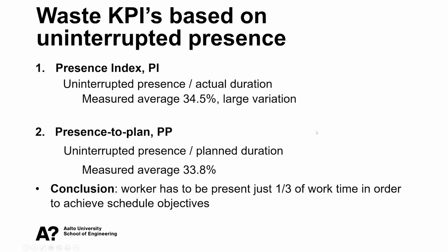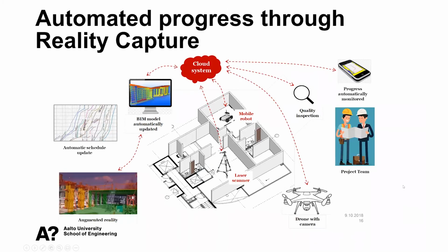Of course, this is just measuring how well you are doing, but to fix this problem, you need situational awareness, basically know what's going on in all locations, and for that, reality capture technologies can be useful. So you can have a lot of different ways how visual data can be captured from projects. Laser scanning is already being used in more advanced projects on a daily basis to do point clouds, which can be compared with BIM models to evaluate progress.